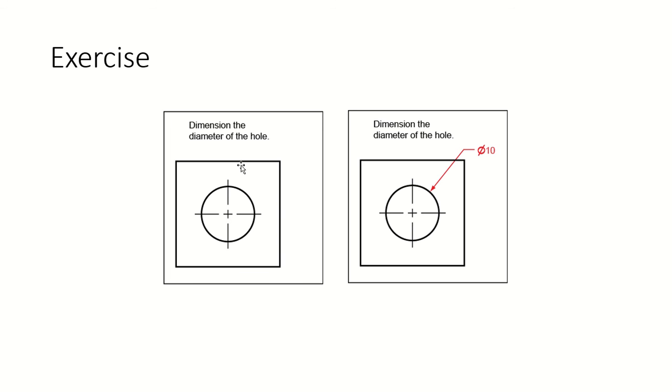So here we're going to put a dimension of the hole. I have a hole, and I'm going to put a diameter. I'm going to use a leader line, and we're going to use a note dimension. I'll put my symbol, diameter, and then I'll put my value. What's been given to me, the specification, of course, from your sheet, and put it in. Oh, that's the diameter, 10 circle.